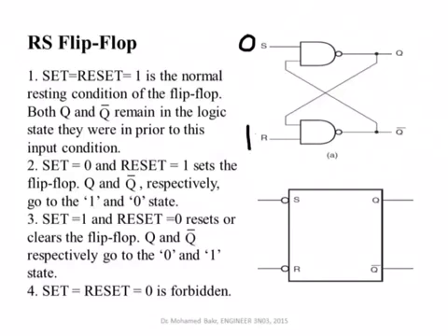Now, if I put 0 here and 1 here, if I put 0 here, this is a NAND, so this Q becomes 1, so you get 1 here at the output. And if this is 1 here at the output, and this is 1, then the output here must become 0. So here, this is your Q bar output, this is a set condition. Set condition meaning it's an active low, so when you put set equal to 0, the Q will be equal to 1. So 0 and 1 will result in a set condition which is 1 and 0. Q is 1 and Q bar is 0.